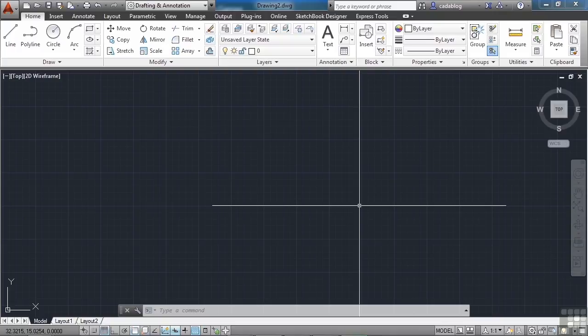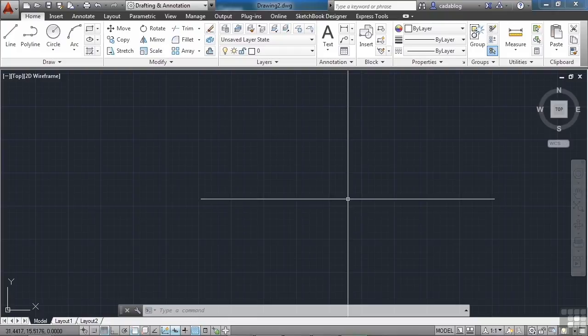The solid command and the donut command are two different, unique commands and object types in AutoCAD. The solid command creates a 2D filled polygon. The first 2 points define one edge of the polygon. The third point is diagonally opposite of the second point, and the fourth point is diagonally opposite of the first point. That's confusing, and I agree with you completely.